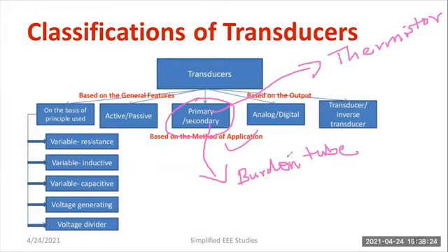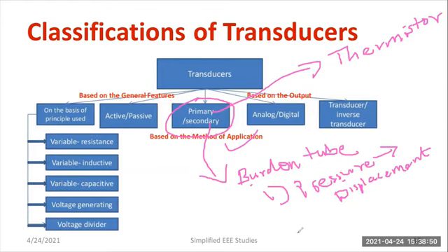It involves two transferring stages. The first step is that pressure will be converted into displacement first. You know what displacement and pressure are. Regarding the second stage, the displacement will be converted into voltage with the help of LVDT.